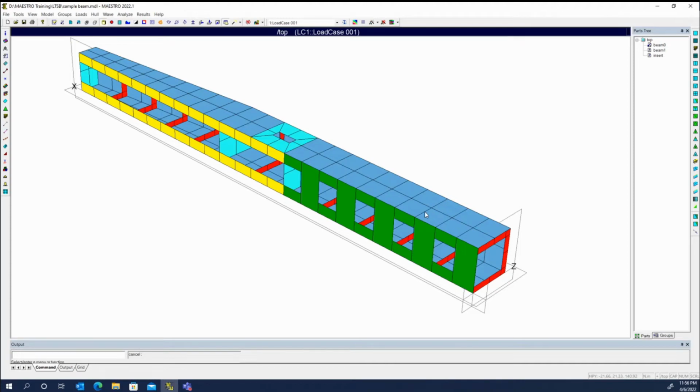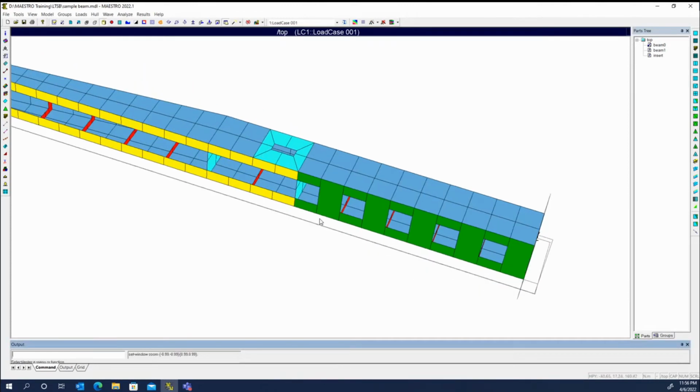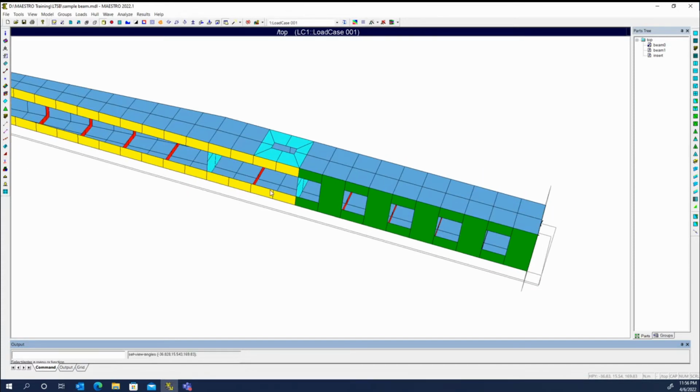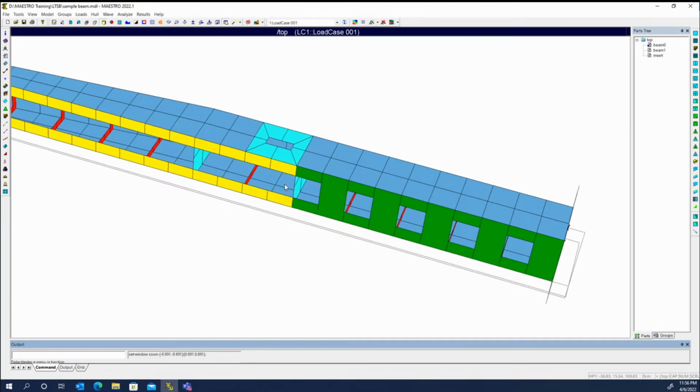So I guess the next thing I wanted to talk about was copying, because once you create these things, it's a bit labor intensive to create everything from scratch. So it's nice to take advantage of existing elements and using the splitting or copying abilities. So we made this set of elements. We converted the straight quads into regular quads and then split them and moved the nodes and created this opening in the upper beam. And let's say we want to recreate that on the lower beam.